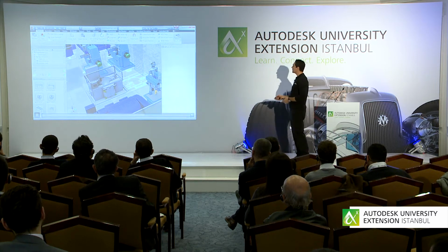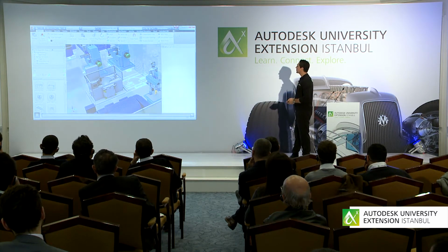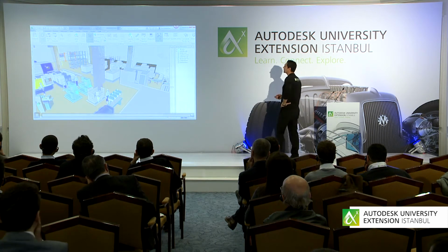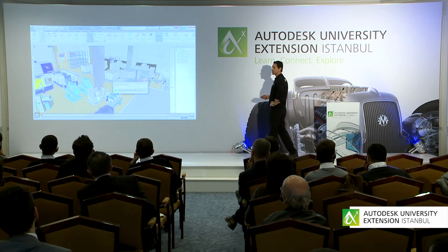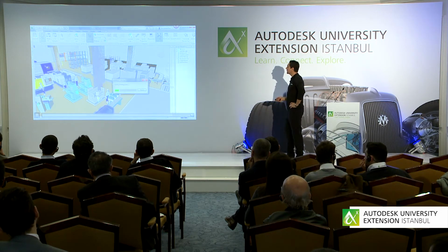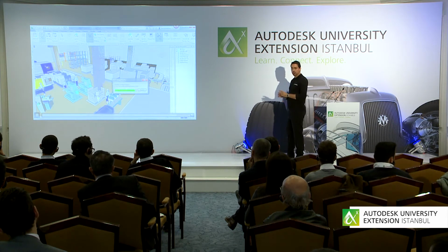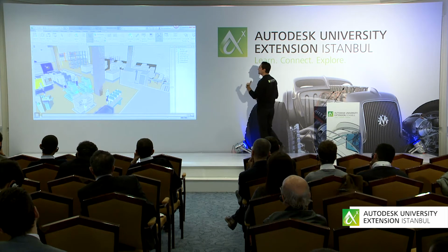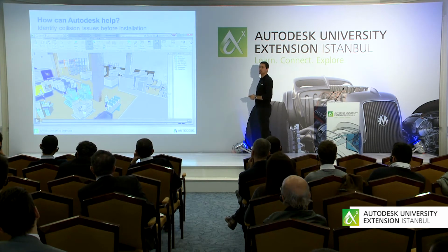So you could see here there's a new location for that equipment. And then from there, you can rerun the report or refresh the actual 4D. And then that should clear off that clash as well. And then you basically go through each clash item itself and rectify and fix it.